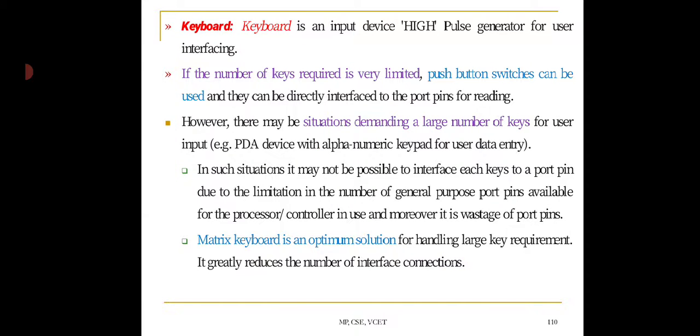Next, keyboard. Keyboard is an input device, a pulse generator for user interfacing. If the number of keys required is very limited, push button switches can be used and they can be directly interfaced to the port pins for reading.